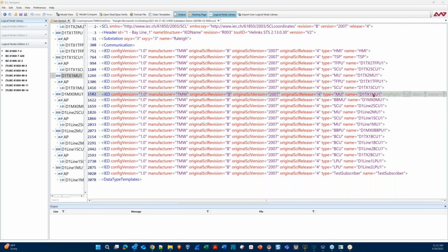All right. So what you see up on my screen now is SCL Navigator. So SCL Navigator is, let's call it, a 61850 aware editor. It allows you to create SCL files, typically ICD files, and other files that are used earlier on in the engineering process. But you certainly can open, edit, tweak, and make changes to any SCL file from any point in the process. A lot of times when we bring it up, we're talking about its validation capabilities.